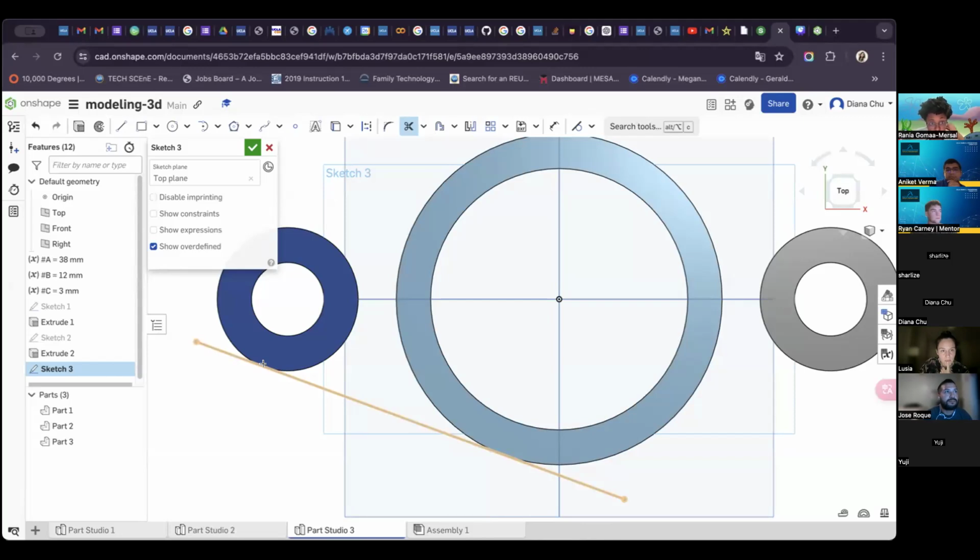Basically you've already made your extrusions. So that line is actually not coincident to anything, or not defined by anything which is in a sketch. It's just tangent to the two extrusions that you made. So instead of doing that, if you can go back into your first sketch and then make that tangent line, then you'll be able to trim off the excess. Oh, got it. Okay. Thank you. Yeah, no worries. Of course.